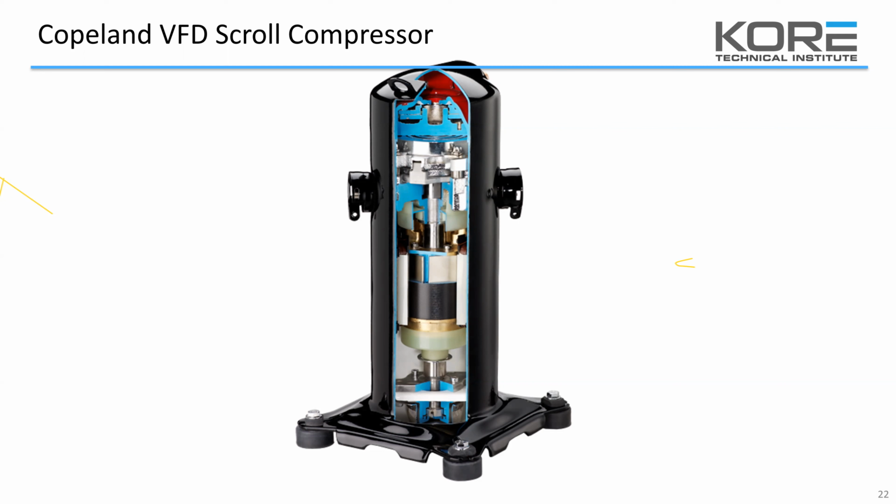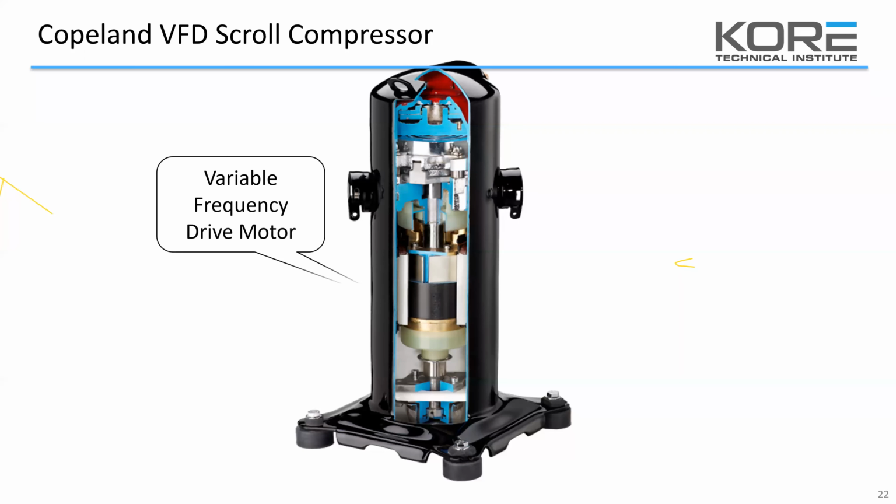I don't know, in this slideshow, there's no slide here showing the effect of the dynamic operation of a scroll compressor, but scrolls require kinetic inertia. They require the spinning inertia of those scrolls to seat the scrolls and effectively allow it to compress. So if you start slowing a scroll down too much, the scrolls can't seat against themselves and it effectively can't do any work.